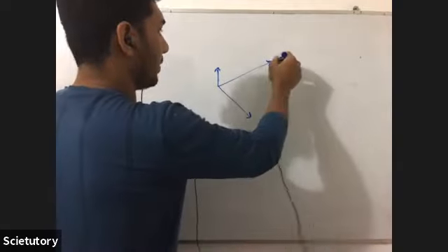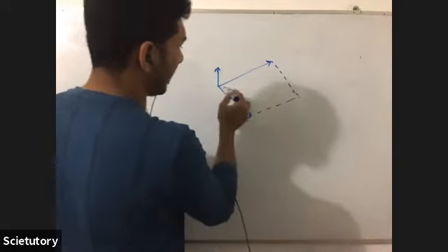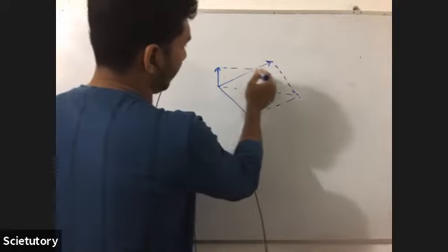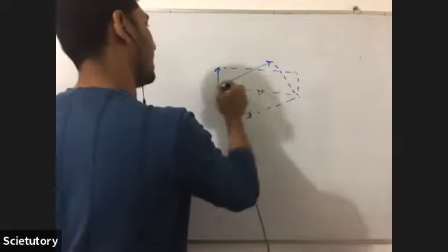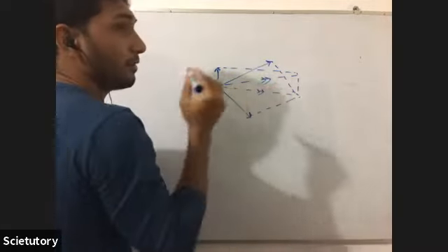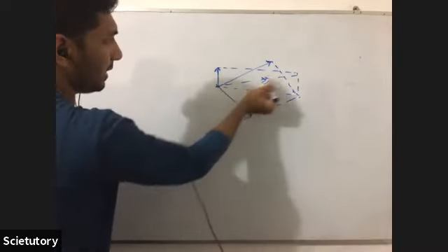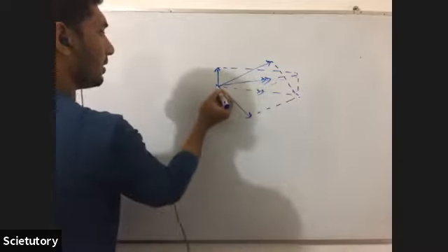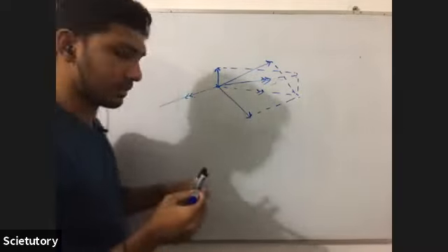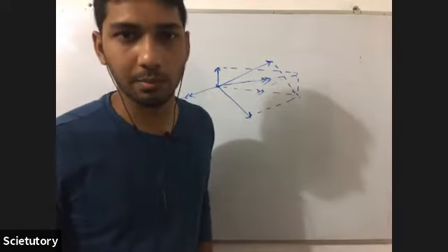Okay, so now you can first draw a parallelogram for these two forces, and this is the resultant, and then you draw a parallelogram for these two forces, and this is the resultant. Okay, so the force that should be applied to keep this object stationary should be opposite and equal to this force. Am I correct? So it is OB here. Please try to draw on the paper itself.